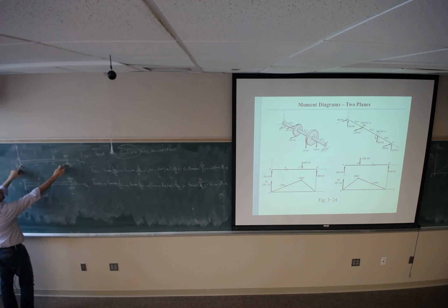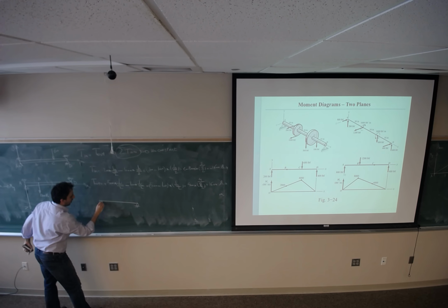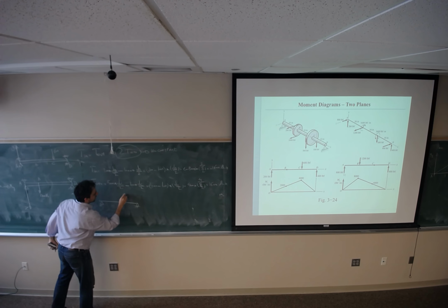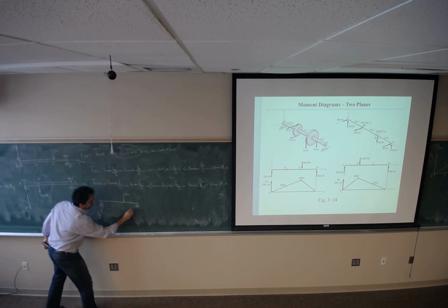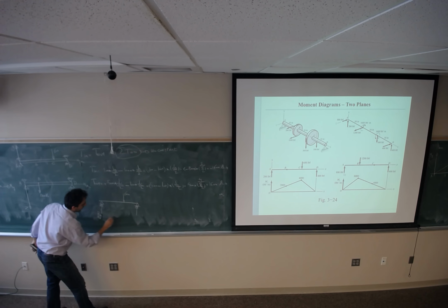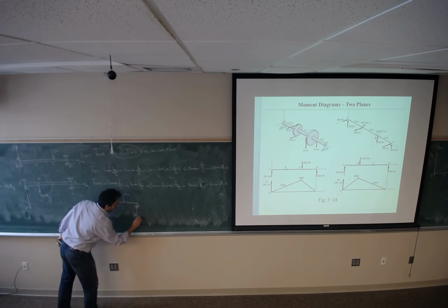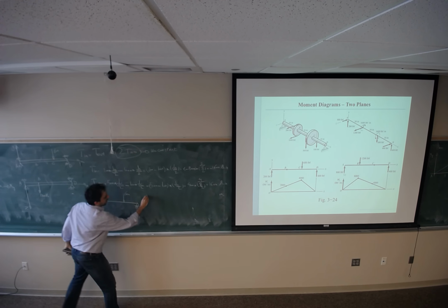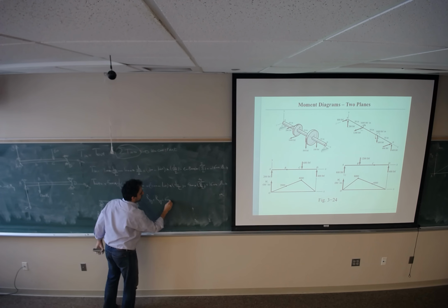I'm looking at this. I have a beam with 600 applied here. I'm looking for R in Y direction, R1 or RA, and R at D in the Y direction. Summation of R should be 600 pounds.